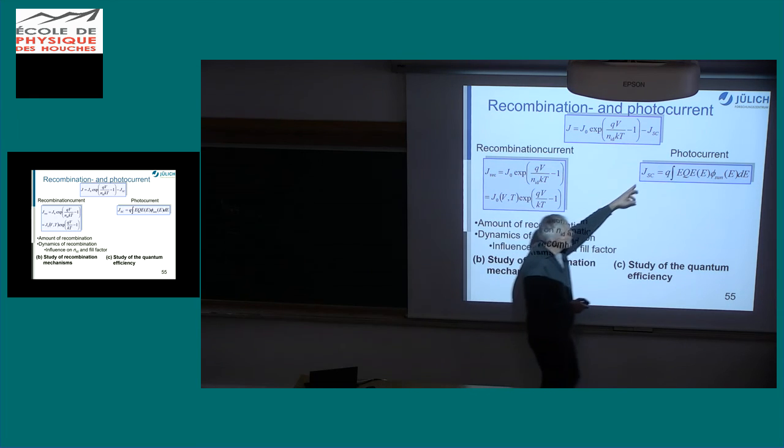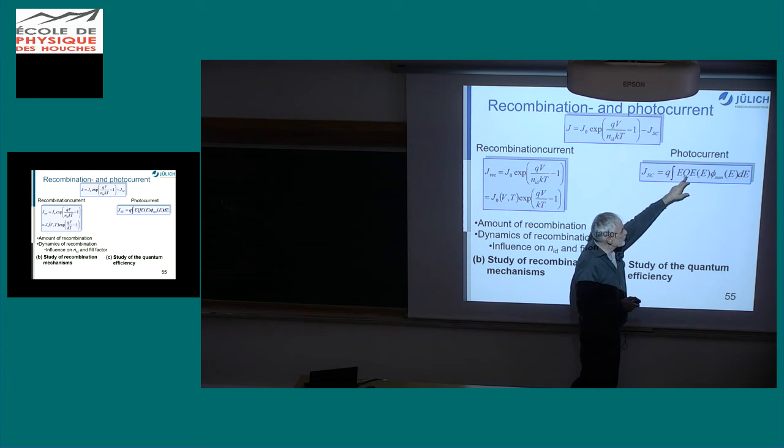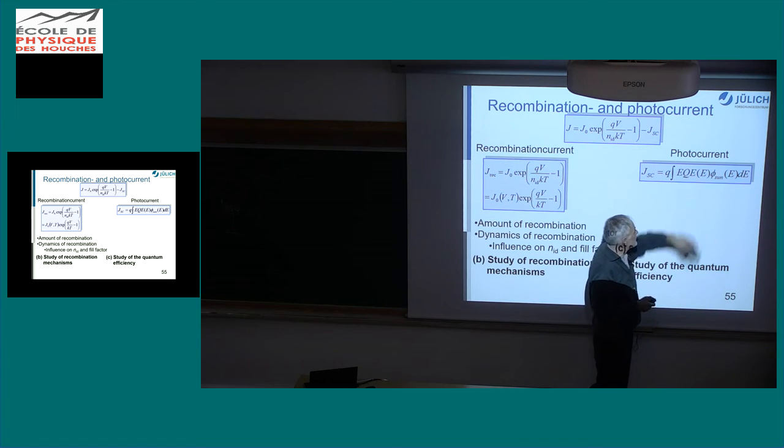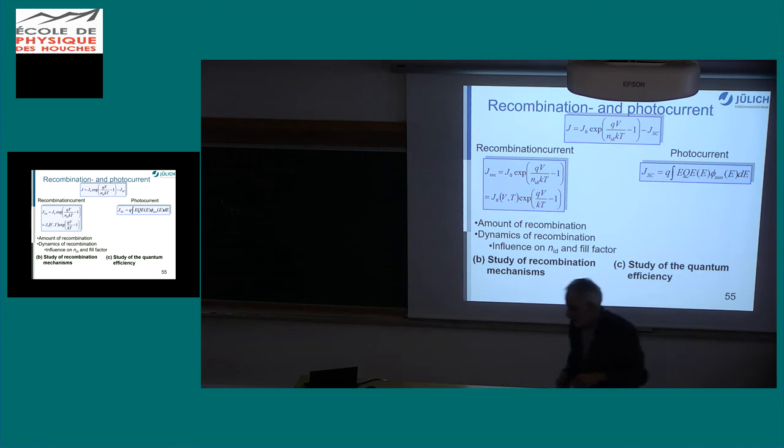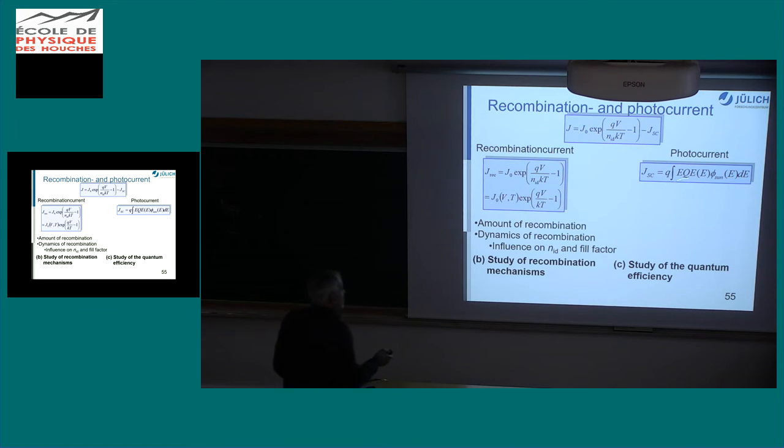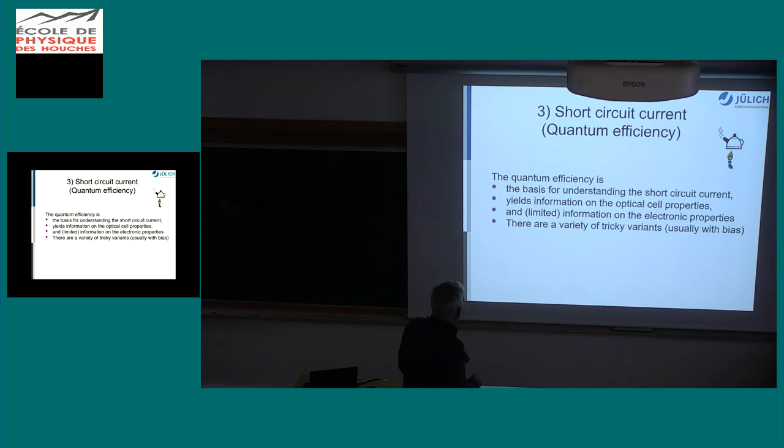and the photocurrent now is JSC times Q, and you have seen this before, integrated over the sun, but we went from E gap to infinity without that term, implicitly saying, okay, my external quantum efficiency, which is here, is just making this step function from 0 to 1, and then you can omit that and just replace it by the integration limits. But in a real device, you have this external quantum efficiency, and if you integrate it over the solar spectrum, that gives you your short circuit current.